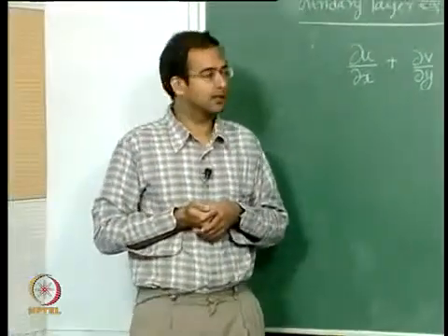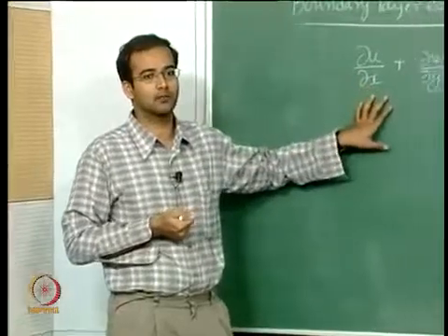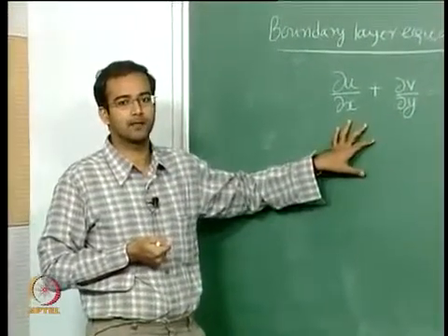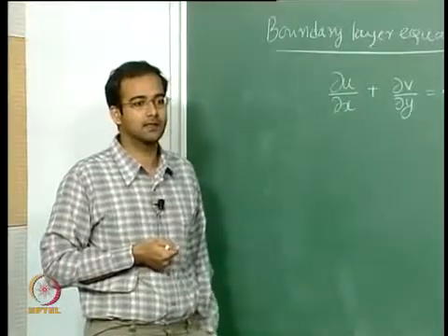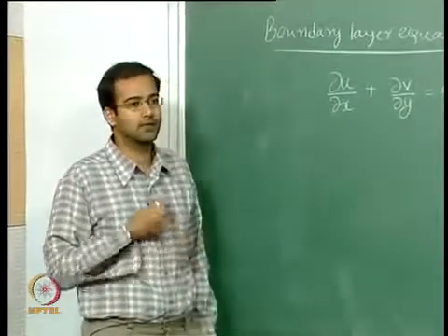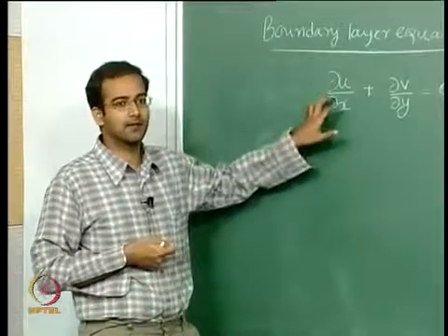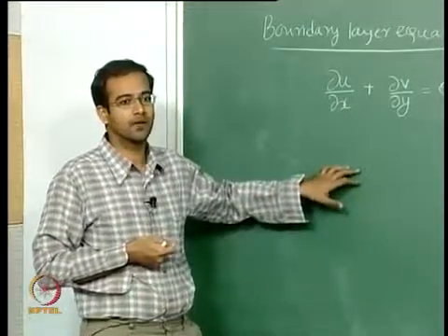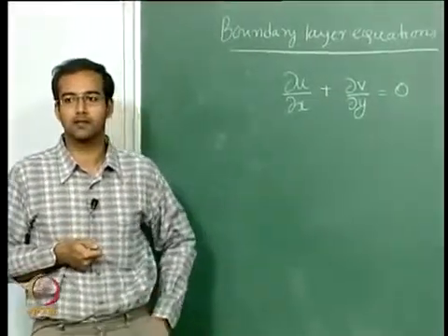When Professor Kolar comes, I think he will discuss how we average the corresponding equations and then we get the Reynolds averaged Navier-Stokes. Structurally everything will look similar. Apart from the laminar stresses, you will also end up with a turbulent stress term.